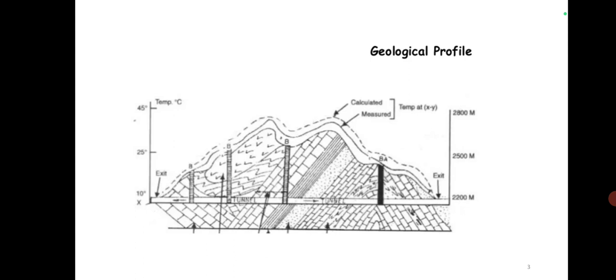Then igneous rocks like granite, diorite, syenite, gabbro and basalt are all very hard, consolidated and crystalline rocks, so these are also favorable for tunneling. Similarly, sedimentary rocks like sandstone, limestone, dolomite, quartzite, and metamorphic rocks like marble, gneiss, phyllite and slate are different types of consolidated rocks. Consolidated means they are hard and crystalline, and they are favorable for tunneling.